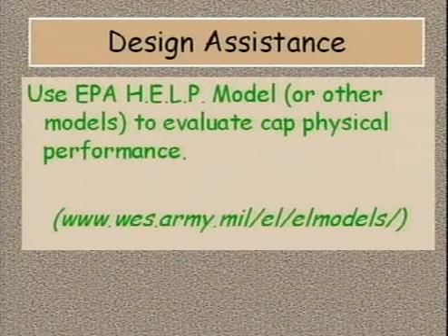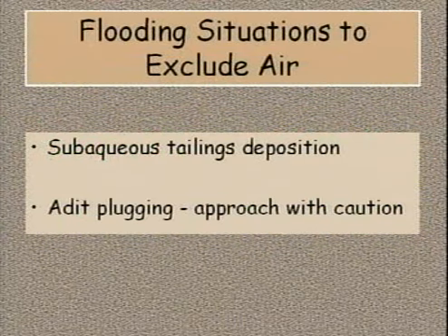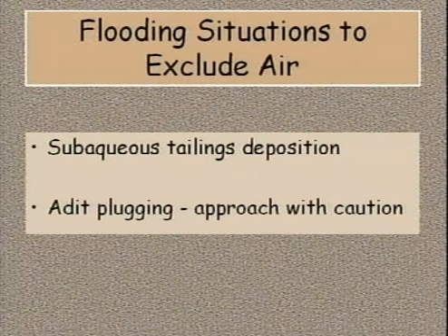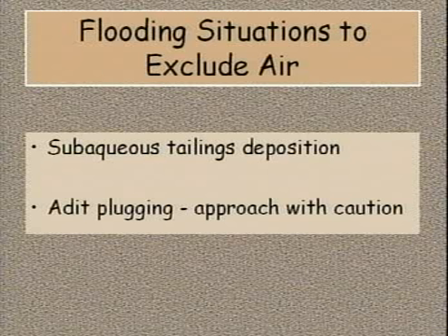Soil and organic material caps can work well to keep water and air away from ARD wastes. But somewhat paradoxically, water can be used to keep air away from mine waste as well, and thus disrupt a different leg of the ARD tetrahedron, the air leg. It doesn't take much, as little as 3 feet of standing water, to suppress oxygen transfer that supports pyrite oxidation.